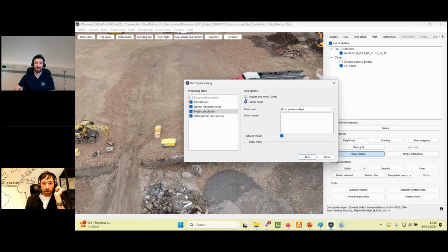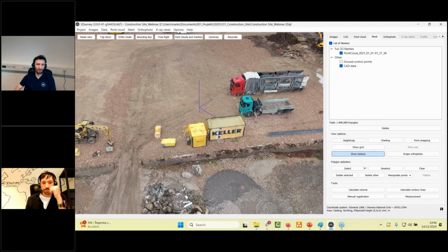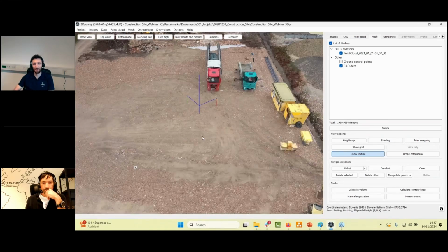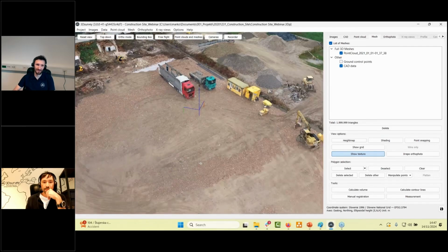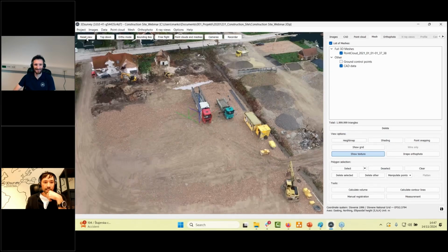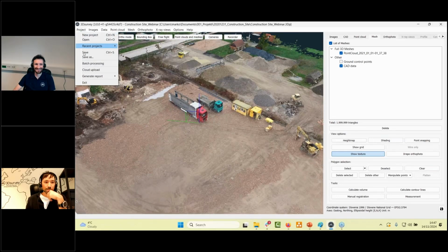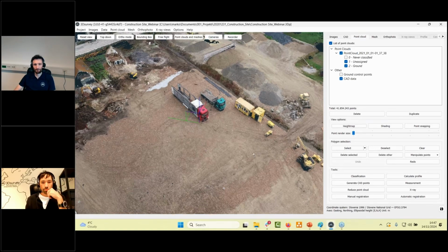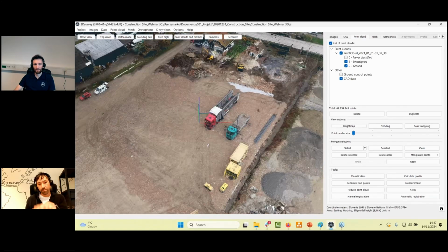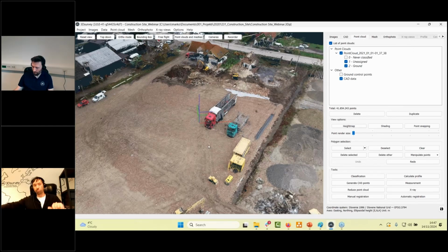Okay. Maybe Marco, on this point, we could emphasize why it is beneficial to go manually over this, since batch processing does not support this step. Exactly. There is a setback of the batch processing. What you're not able to do with batch processing is classify point clouds into terrain points and everything else. So if you need to do the classification to calculate the digital terrain model, you need user interaction here and click on the classification feature.